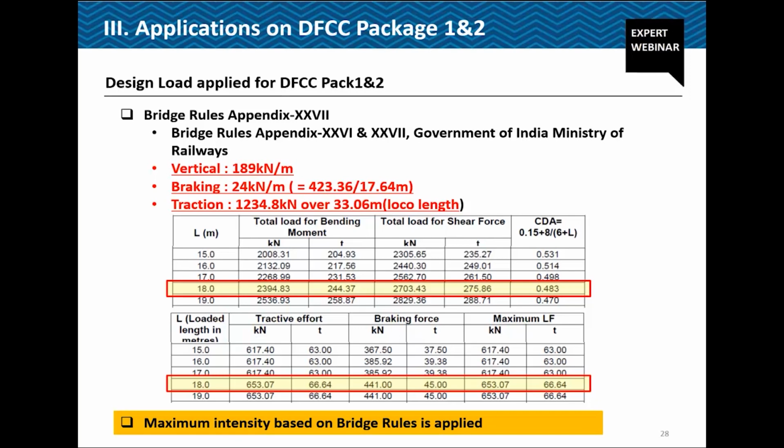The basis of this table is that if we have an 80 meter span, whatever the 5 load combinations or axle combinations, whichever gives the maximum case goes into the table, so that engineers can easily take this number when they design the bridge.